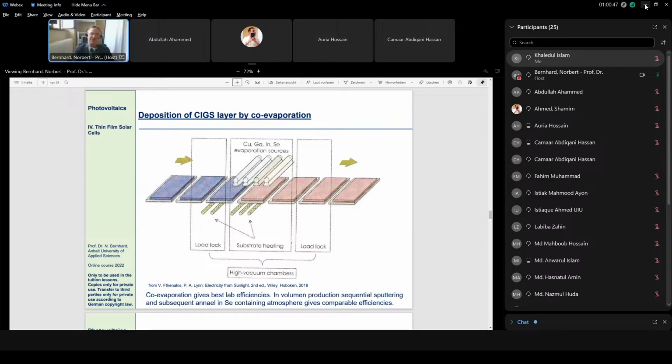and then it could be transferred to an electrode. Optionally, we could have here a layer which is called an electron transport layer, which at the same time is a hole blocking layer. And here we also could have an additional hole transport layer, which is an electron blocking layer. And this electron transport layer is an N-doped organic semiconductor, and the hole transport layer is a P-doped organic semiconductor. That means organic semiconductors in principle can be doped similar to inorganic semiconductors.